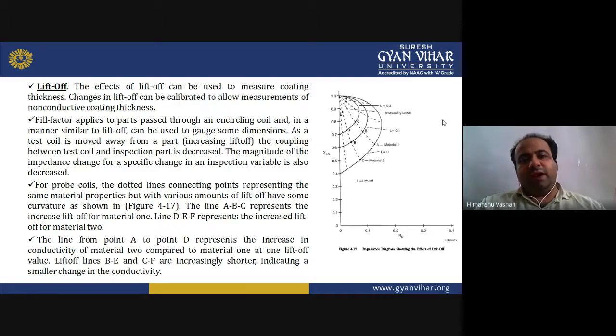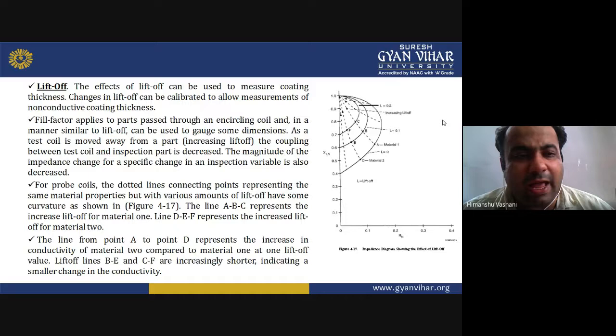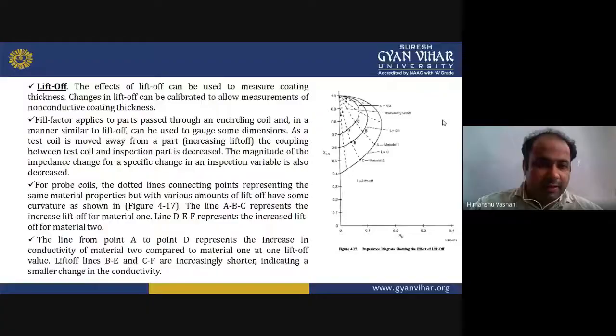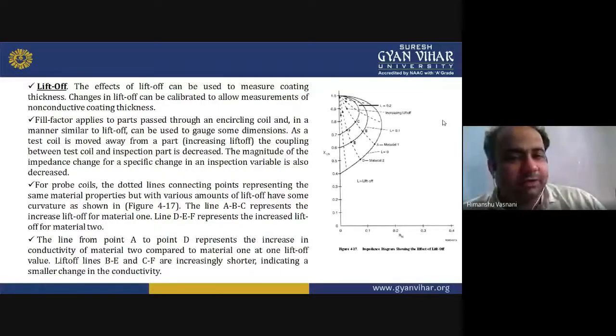A fill factor applies to parts passed through an encircling coil, in a manner similar to lift-off, and can be used to gauge some dimensions.